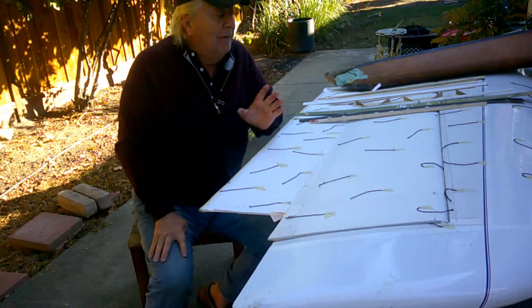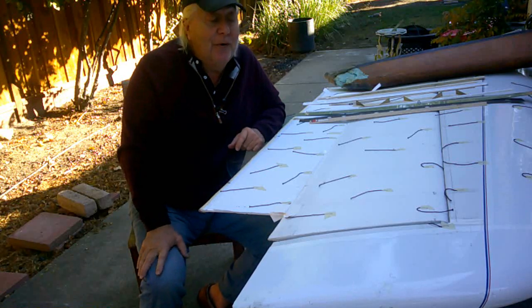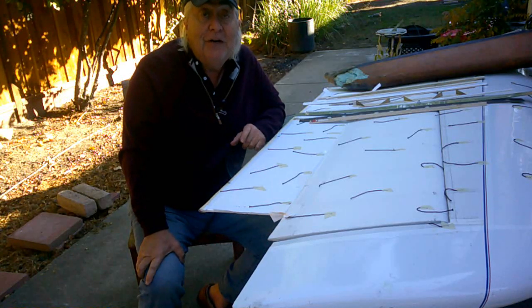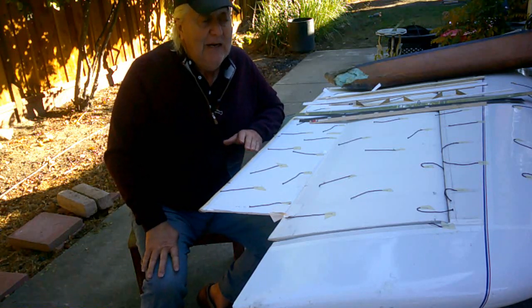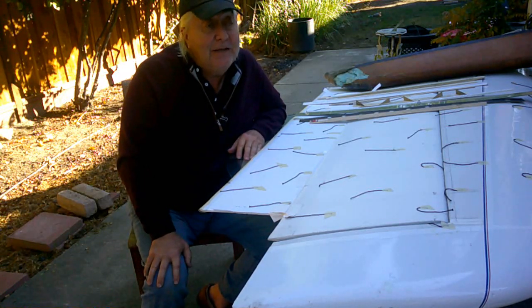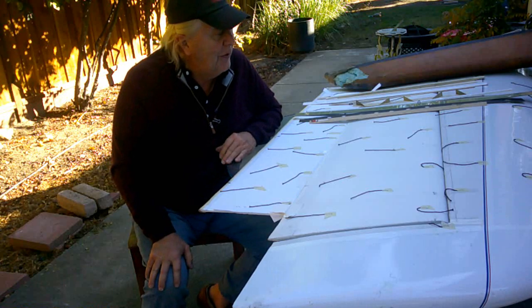In fact, same problem. Flow begins to separate. I put in more elevon, it separates more, and yaws the wrong way. Problem. Okay, especially a problem when it yaws the wrong way. Just the natural reaction is to put in more elevon.